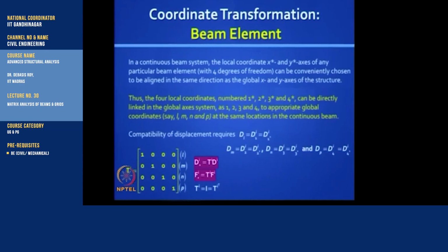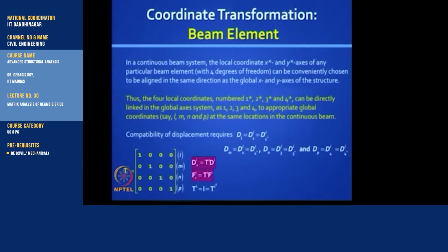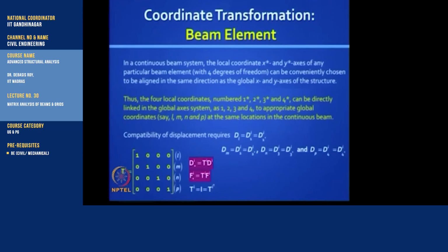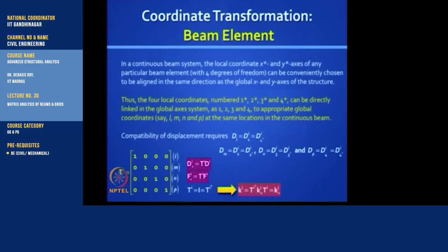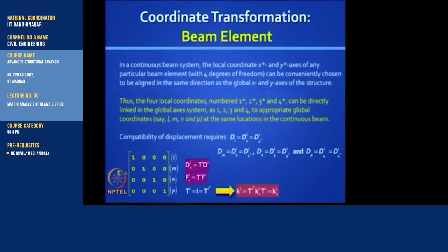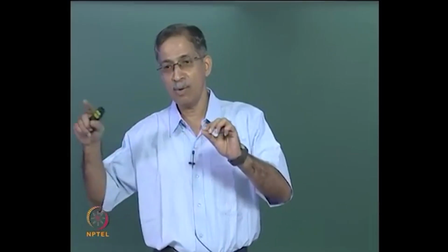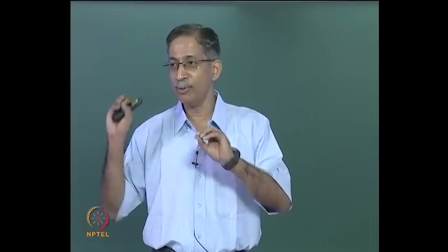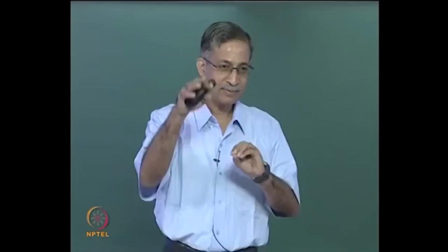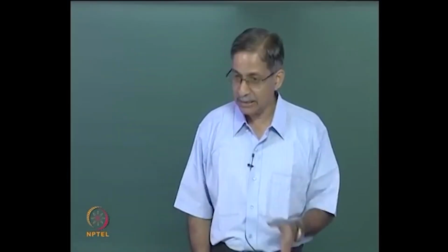So the beauty about the identity matrix is the transpose of this matrix is also an identity matrix, and so if you try to convert the element stiffness matrix from the local coordinates to the global coordinates, you get back exactly the same matrix, except along with it you will get the linking global coordinates, which is crucial for you to do the slot wise adding. Okay. Is it clear so far?